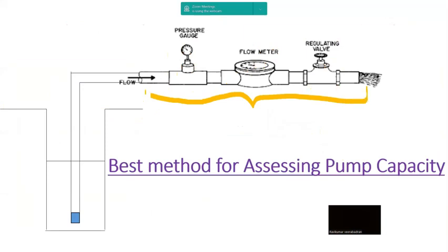You will get better data when you connect this setup with the outlet pipe, and this is a pump, this is a well. You can control the regulating valve and increase the pressure at this place to be 10 meters or 15 meters or any design pressure you want.